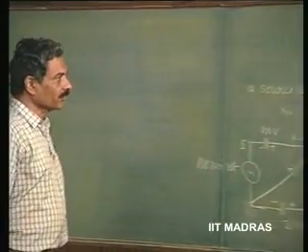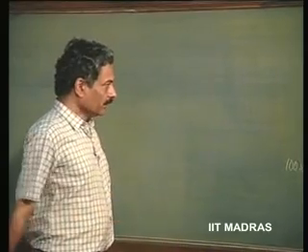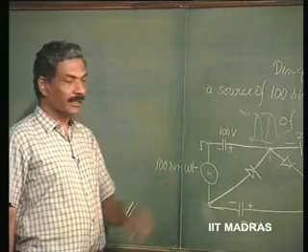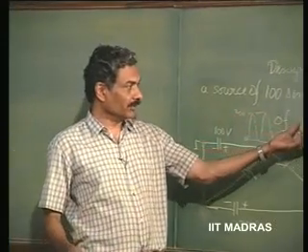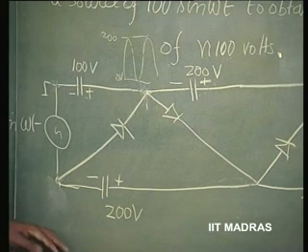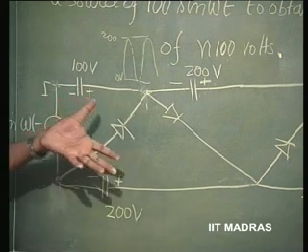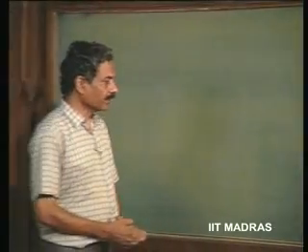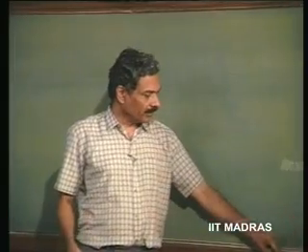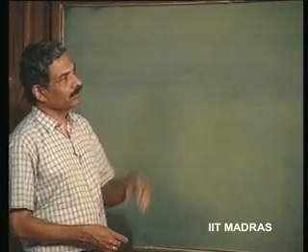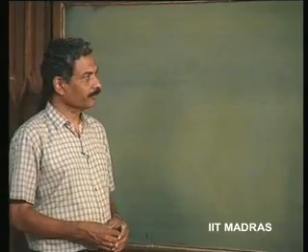Then you can sustain this voltage as a large high voltage from this common point or this common point, depending upon the kind of N you are going to select. So this you can test in your laboratory very easily by using simple diodes and capacitors. This is one example that we have learnt how to solve by learning about what is called the voltage multiplier circuit.